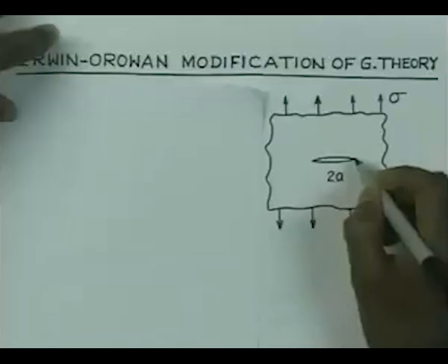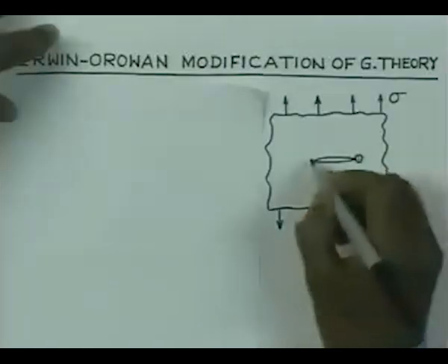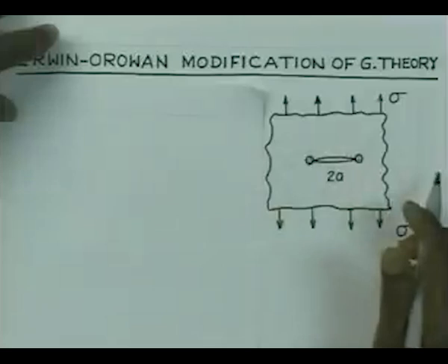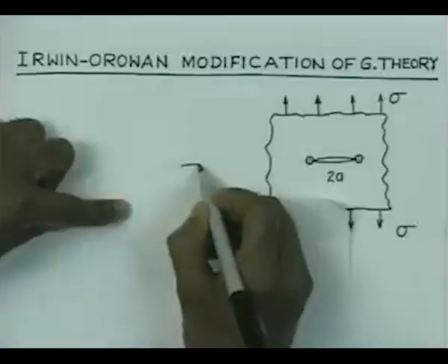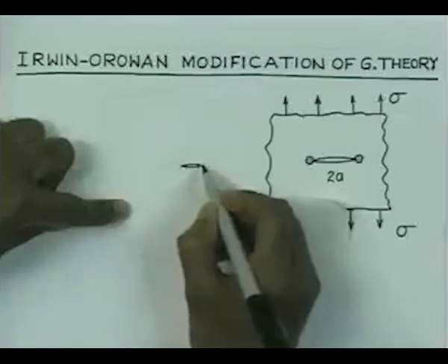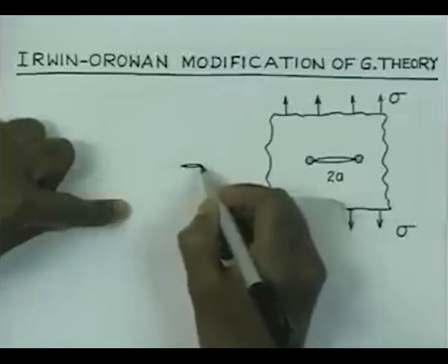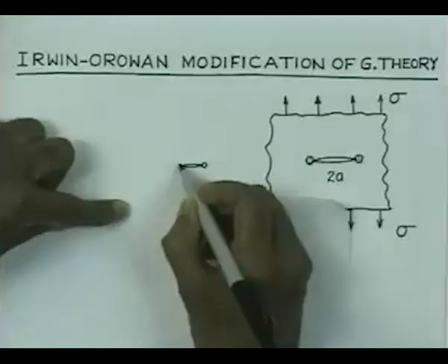So, before the crack propagation can take place, there will be some plastic deformation at the crack tip, since these are highly stressed regions. Therefore, before the crack extension takes place, there is going to be plastic deformation. Suppose that you had begun with a small crack size like this; before the crack extended there was plastic deformation at the crack tip.